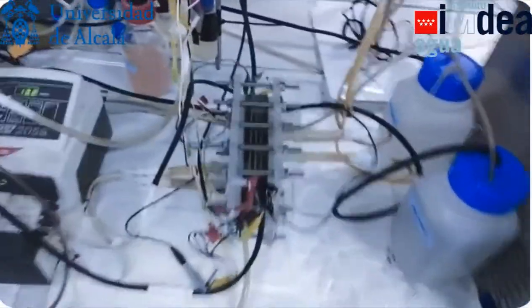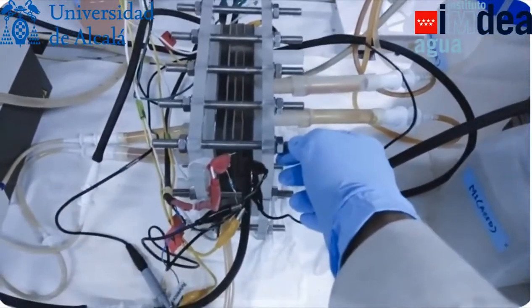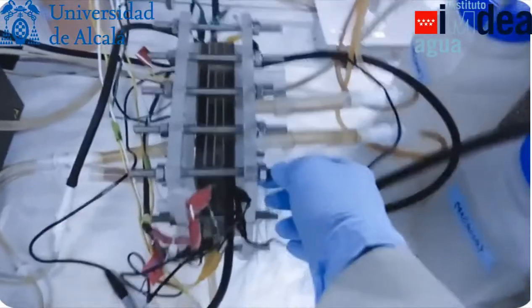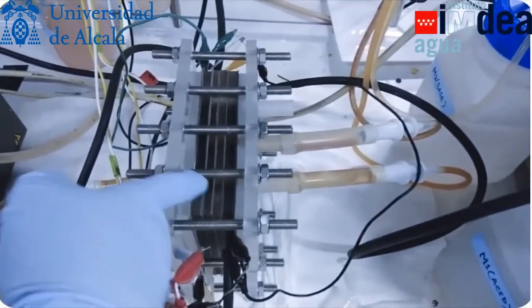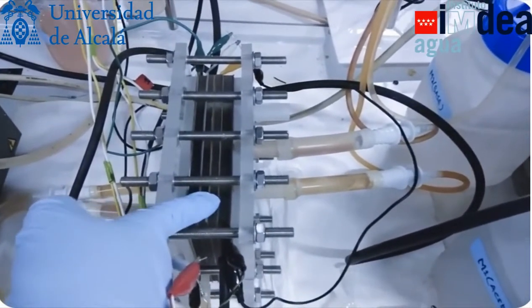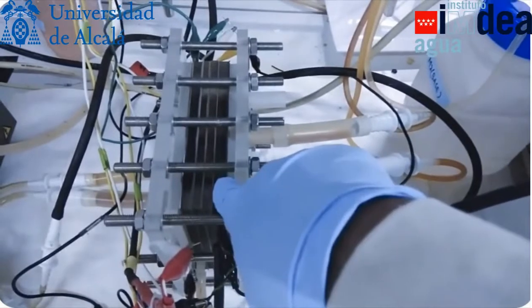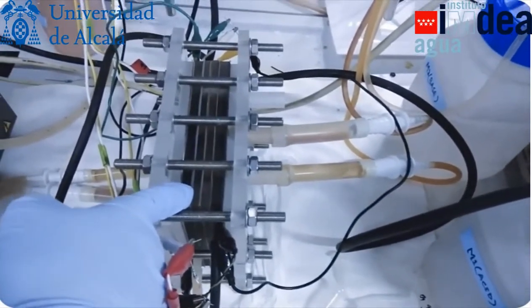So you can see this is my 4-chamber microbial desalination cell which is under operation now. The first chamber in this cell is a cathode chamber, followed by chamber A, that is the acid producing chamber, chamber B, that is the base producing chamber, and an anode chamber. Cathode chamber and chamber A are separated through an anion exchange membrane.